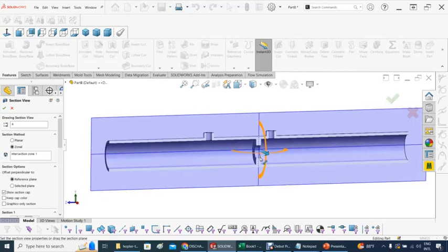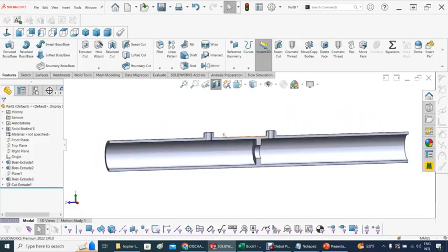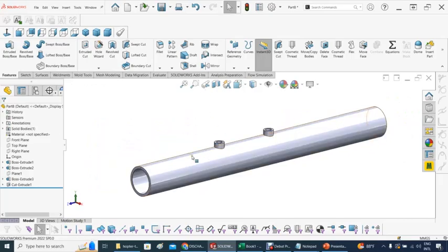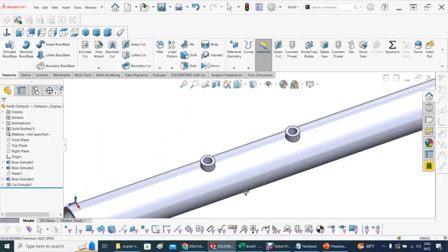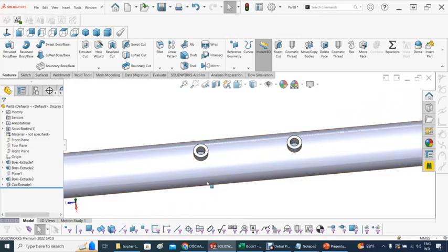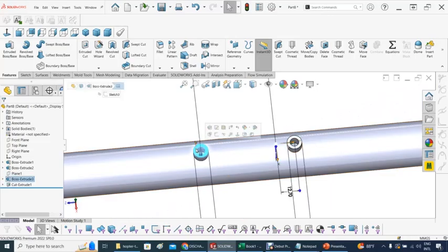Now, the top is to locate kind of a pressure sensor in essence, but we're gonna do flow simulation. So basically, we're gonna put a seal. We're gonna seal these guys so there's no flow out or anything. And so for that, we're gonna put those seals. Let's get this out of the way, and we're gonna seal these guys. So what we're gonna do is create a solid here on that surface.